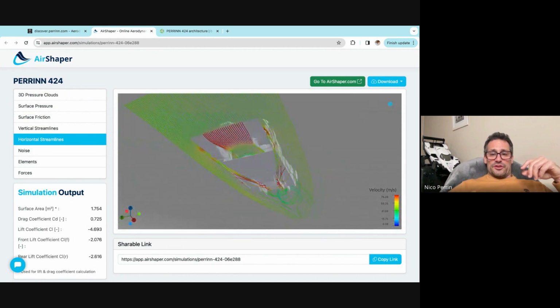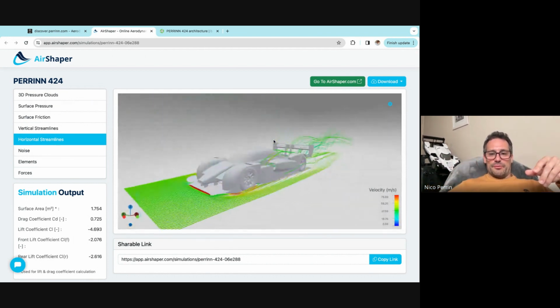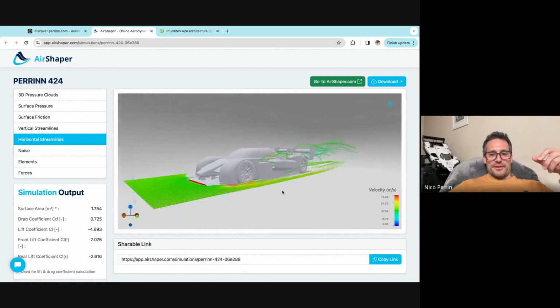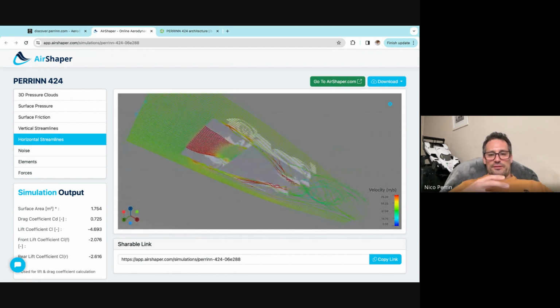In Formula One, actually, most of the floor or diffuser air will come from the center of the car, because it's just naturally working more this way. They don't have the ability to manage the flow around the front wheel in the same way as we do for Le Mans cars. So just know that the way the flow structures are working is different. But all Le Mans hypercars will work more or less as you see here on this picture.